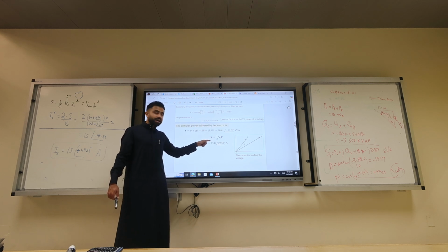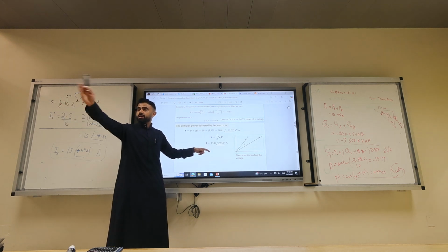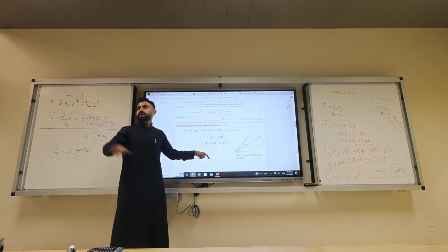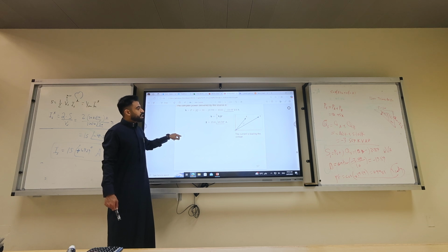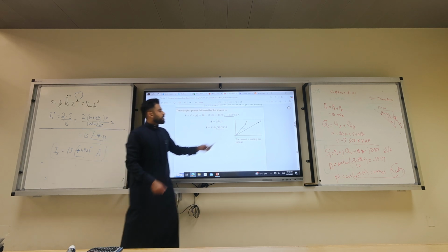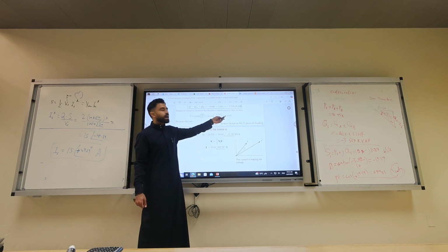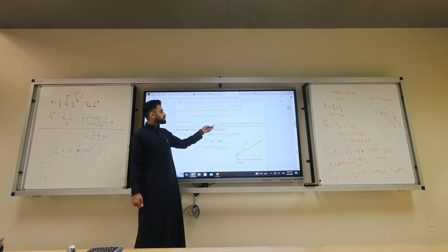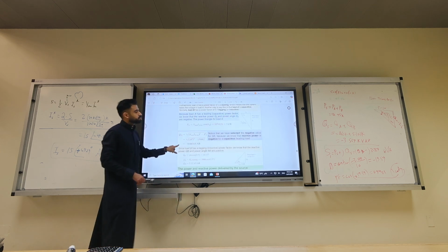And I get it with a minus 49. So I is what you replace minus 49 with plus 49. That's how to convert from conjugate to regular without conjugate. That is this example in a nutshell. And again, the current leads the voltage because we have a negative angle, or the power factor is 0.9421. Try to solve this example at home, okay?